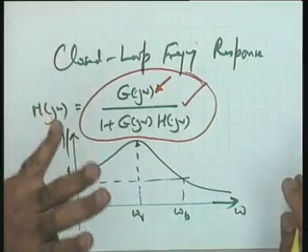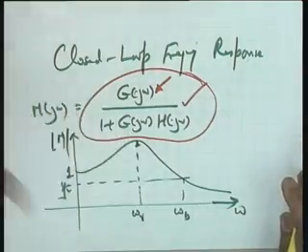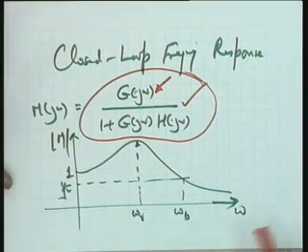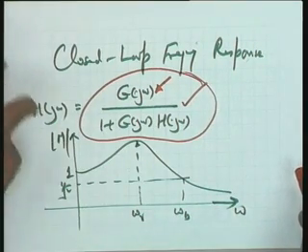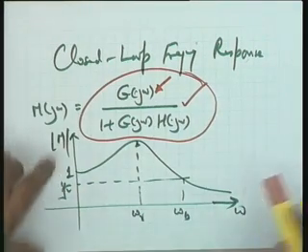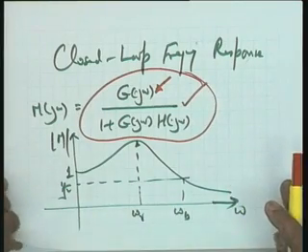For a complete frequency domain description of the system, you will naturally require both the magnitude and the phase response. I am only making the magnitude response because we normally use these indices. The phase margin index brings into our design algorithm the basic features of the phase characteristics of the closed loop system. That is why I am interested only in the magnitude response, and the values of Mr, omega r and omega b are required.